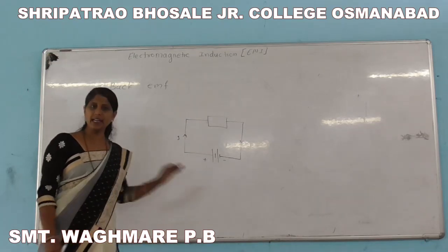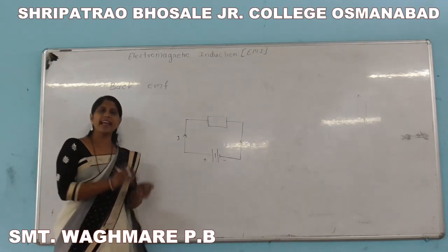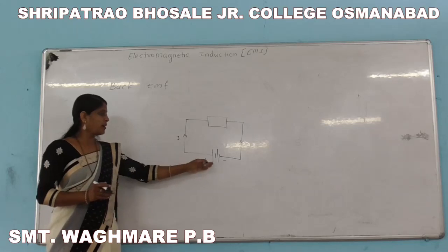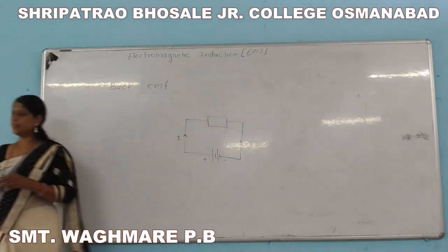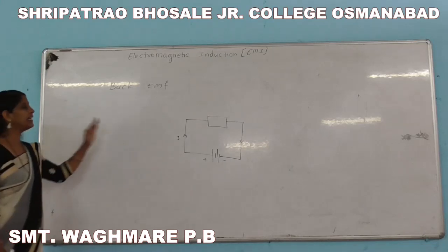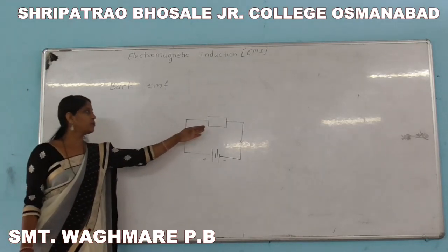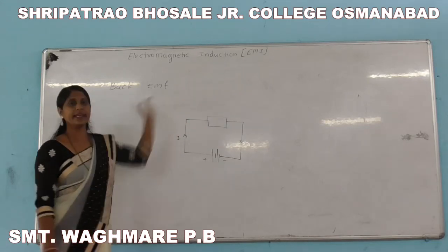It is opposite to the externally provided EMF and current. This induced EMF is unavoidable due to the generator action in the motor, and this unavoidable EMF produced in the motor is called the back EMF.